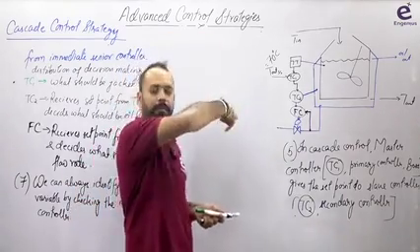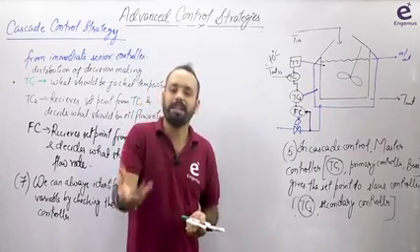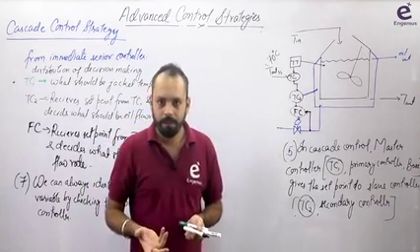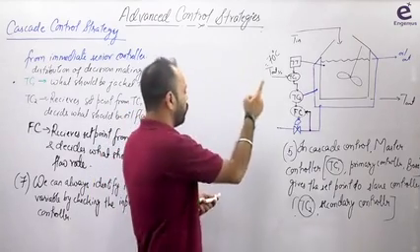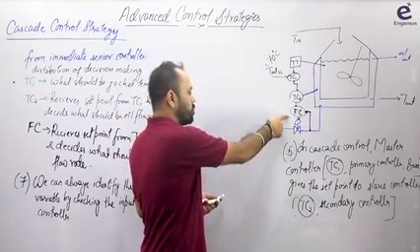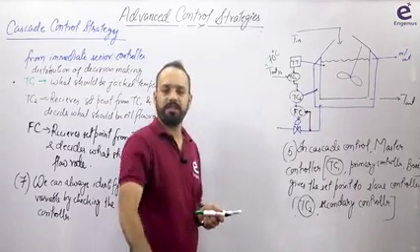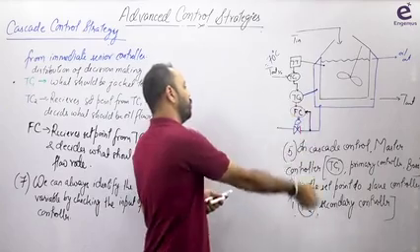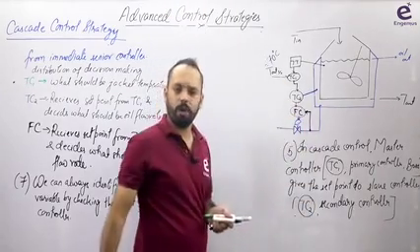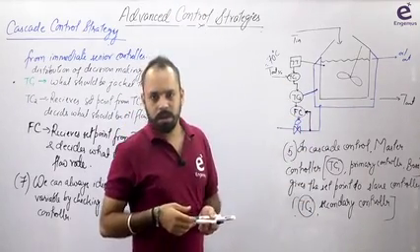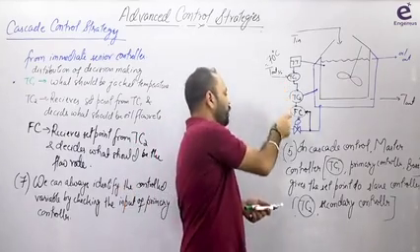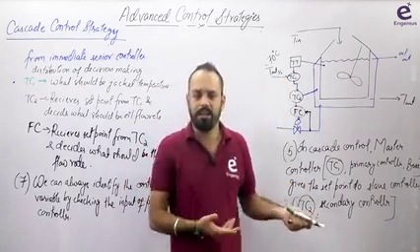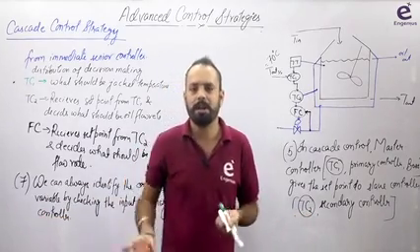अब वहां से कैस्केडिंग. So for cascading to be advantageous, for cascading to be economical, for cascading to be fruitful, the controller which is at the lowest level should be the fastest controller, and the controller which is at the topmost level, who is the boss, should be the slowest controller. मतलब सीधी बात है, ये slowest हो जाए ना हो, लेकिन ये सारे इससे फास्ट होने चाहिए, तो ये अपने आप स्लो हो गया, राइट? Automatically it is, if other persons are fast, then I am automatically slow, right?